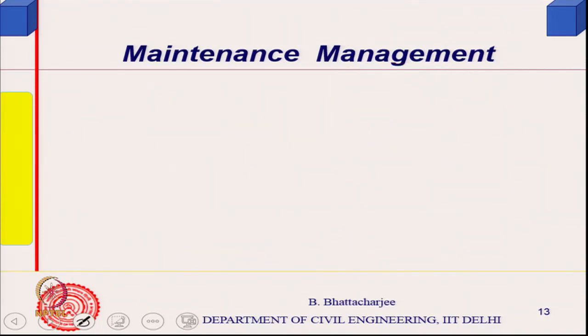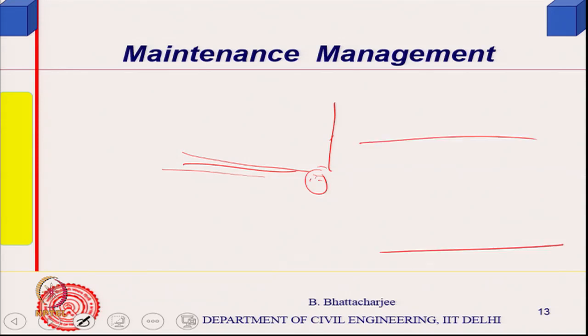if you have, let us say, a section of a flooring, and you have a gully trap here, in the flooring of a bathroom or shower room, in one of the corners, the elevation is like this, and it should have a good slope. But quite often, if it has not been done properly, you might see that the trap is here. In plan, it looks something like this: here is a trap.